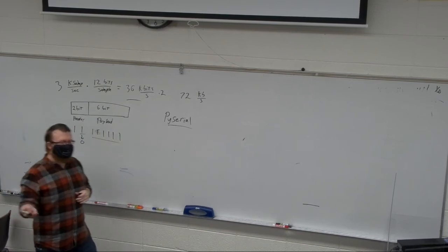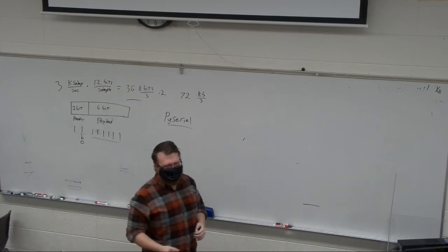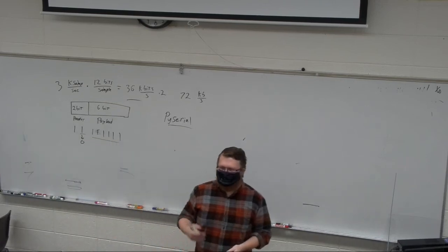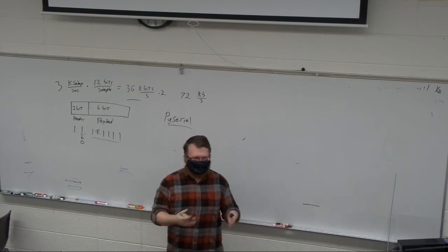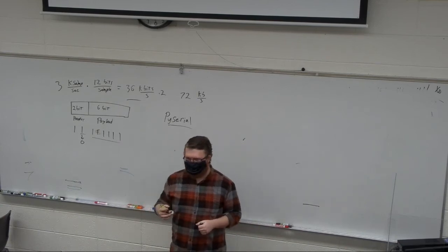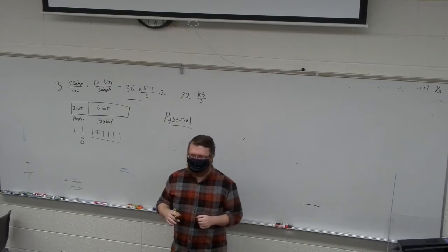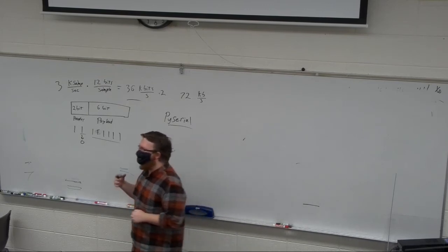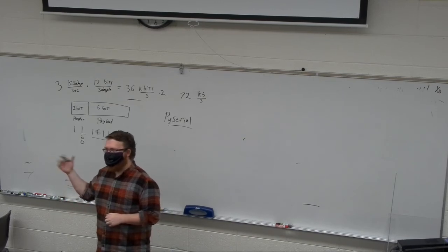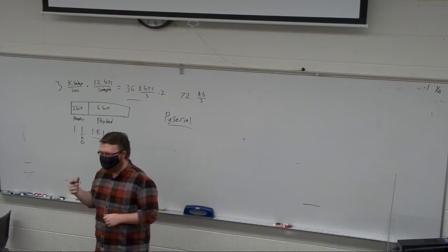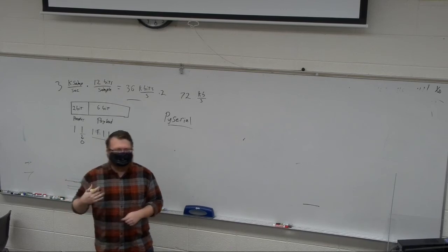So I'm going to give you a requirement, say that it's going to have to record data at 3 kilosamples per second for 1 second after a given user command. So you're going to have to send data either over PuTTY or over PySerial. If you send it over PuTTY, you're going to have to encode your commands in ASCII acceptable format, right? You have to send it an ASCII symbol to get that command out.